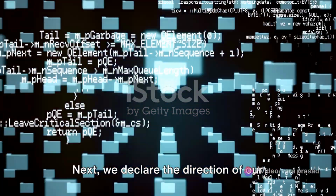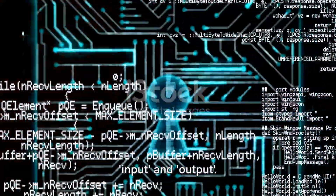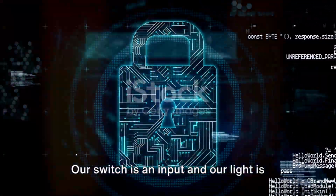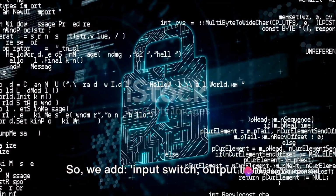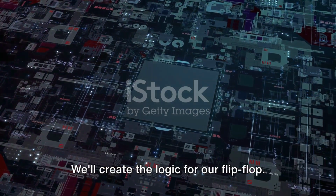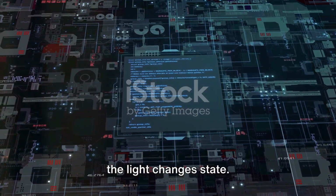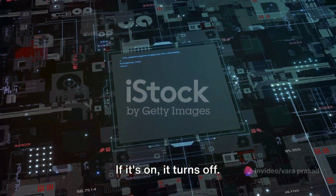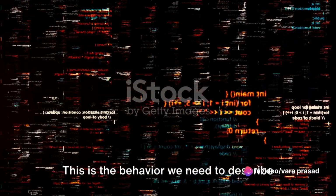Next, we declare the direction of our inputs and outputs using the keywords input and output. Our switch is an input and our light is an output, so we add input switch, output light. Now the fun part begins. We'll create the logic for our flip-flop. In essence, when the switch is flipped, the light changes state. If it's on, it turns off. If it's off, it turns on. This is the behavior we need to describe in our code.